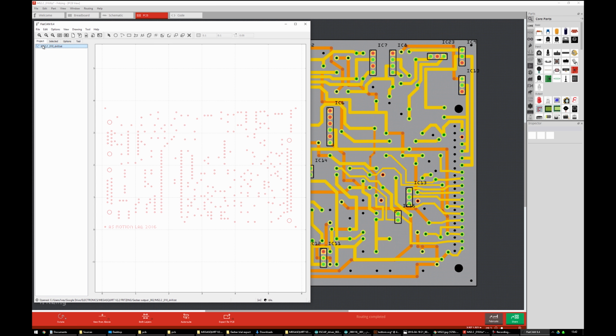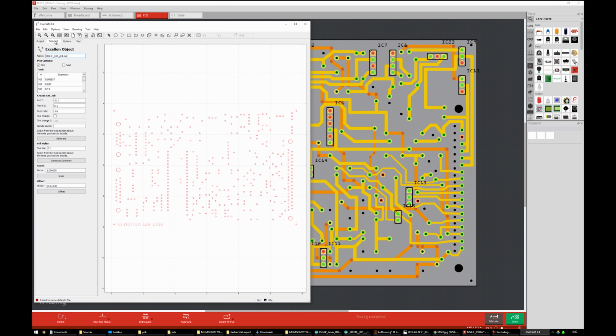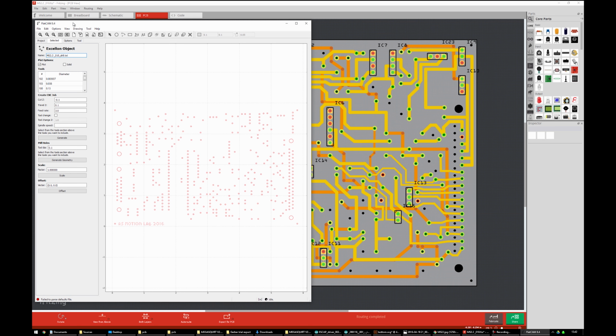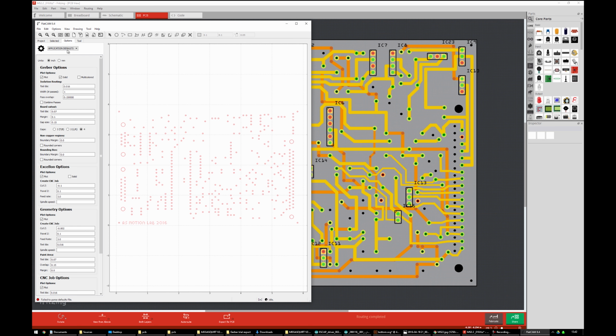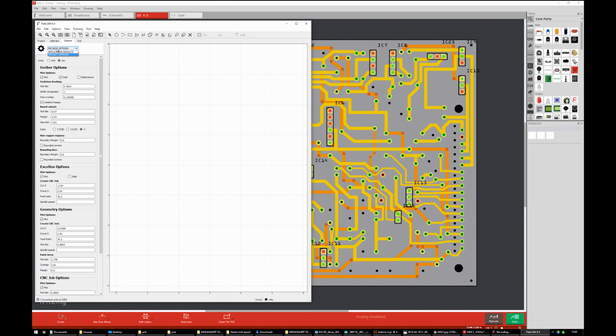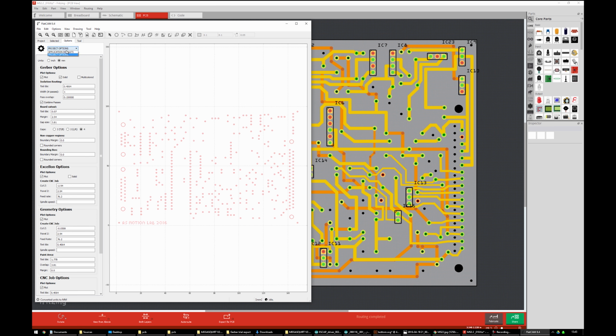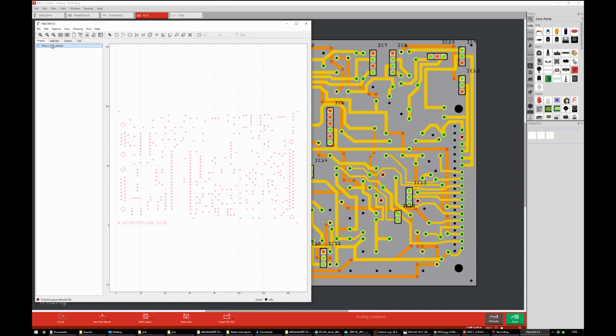So you select the vector, the input file, and then you move into the operations that you can do with it. Actually, just before we do that, I'm just going to set up the units here. Project options, millimeters. I'm using millimeters. Okay, cool. Yeah, so we're using millimeters here. We haven't created anything yet in FlatCam, so we don't need to redo anything.